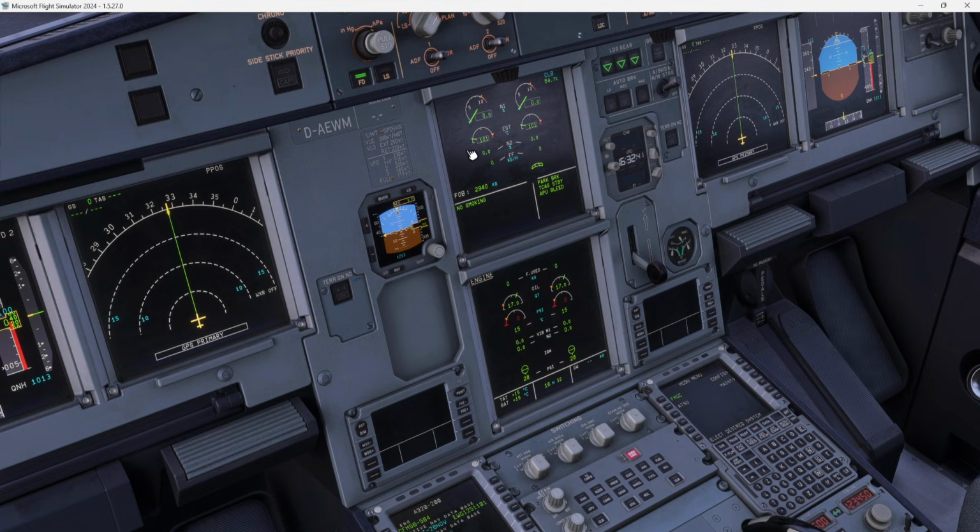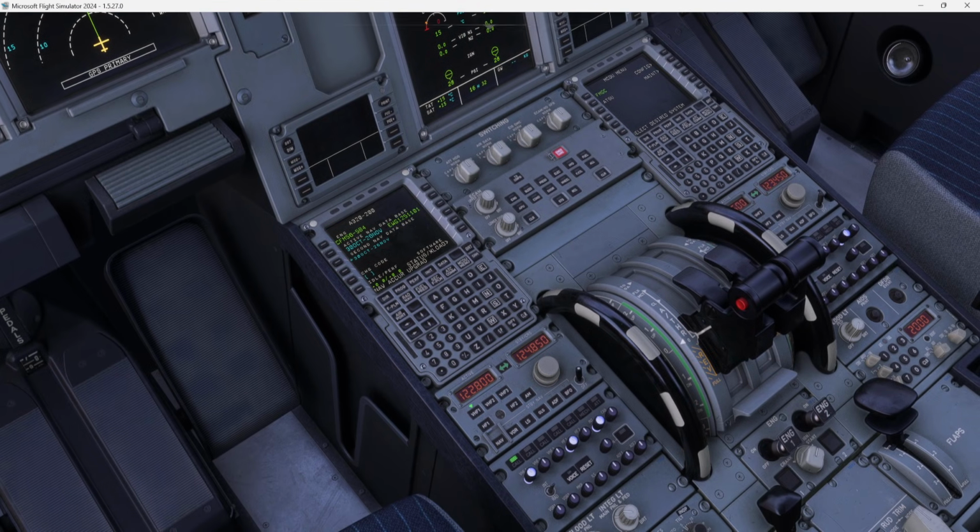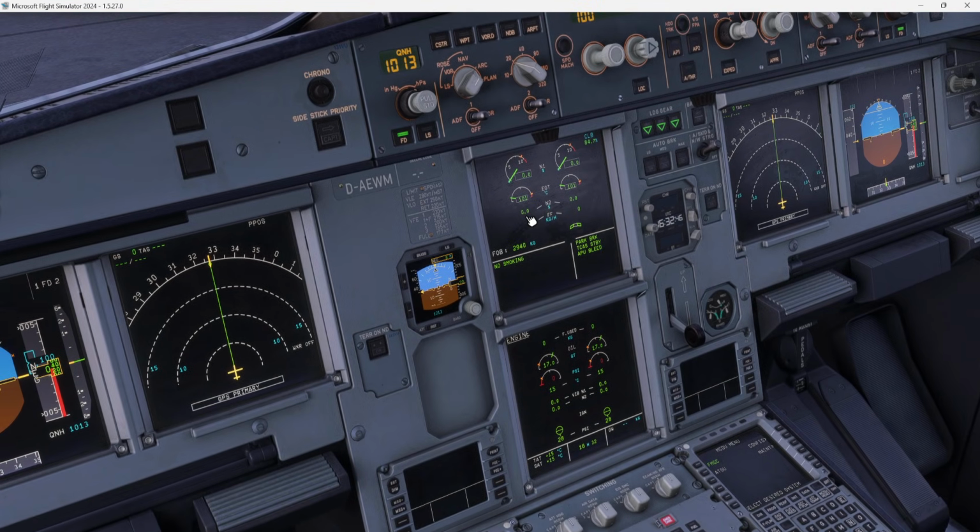Okay, the same thing for engine 1. We are going to start engine number 1. The N2 is going to rise, the high pressure system is going to rise up to 22%. The fuel flow is going to start, so fuel nozzles are going to send fuel into the combustion. Here we are in the combustion. Then the N1 starts rising, and EGT for sure is going to start rising, and we double check the value of the fuel pressure. It is important also. It should rise and stop at 35 up to 60%.